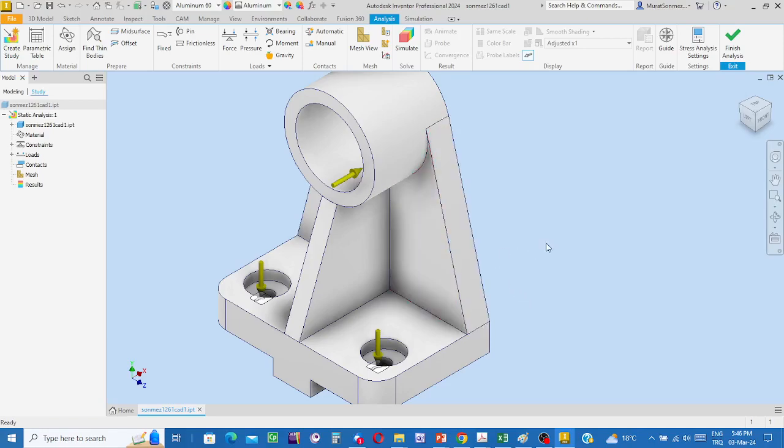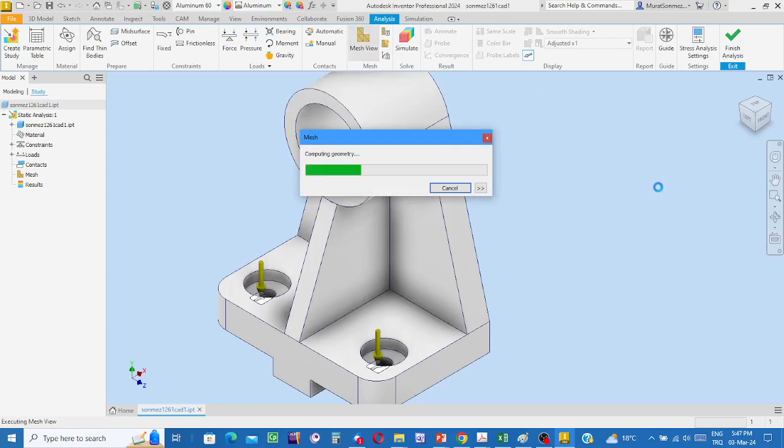and also let the software, using its default setting, use a greater mesh size if the geometry is not changing, otherwise a smaller mesh size. Not manually but automatically. The mesh size is going to be determined by the software. But in the next class meeting, I'm going to teach how the mesh size is changed under the control of the user, and especially how a finer mesh is used at places where the geometry abruptly changes. Okay, see the default mesh by clicking on this button.